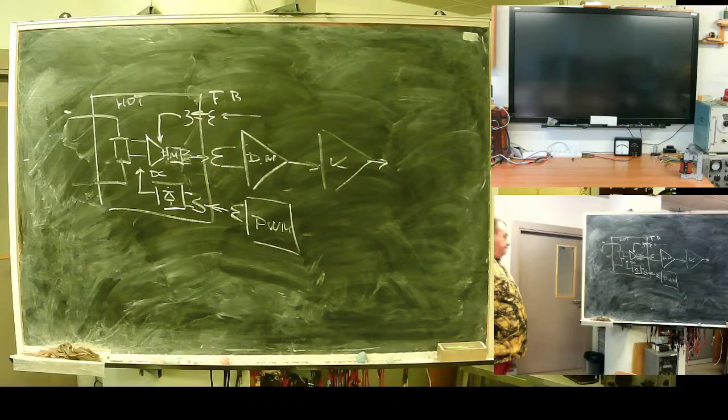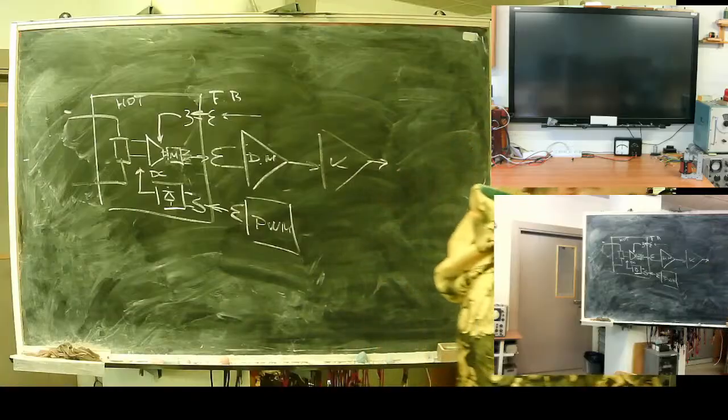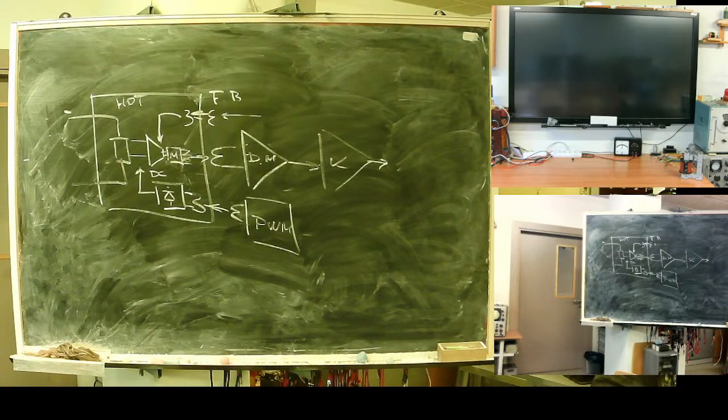To do so, this amplifier can be with a switchable amplification ratio. One of the tricks to ensure the necessary dynamic range is what? Our system has a controlled gain. For example, 1, 1/8, 1/16, and 1/32. Initial measurement is done at 1/32. Or the signal is too low, 1/16. Or still low, 1/8. Okay, we do it. It's a range extension.